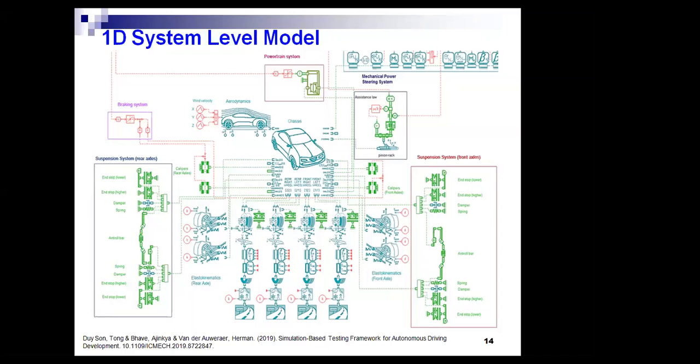Here it basically works based on an analytical approach. There is no finite element modeling or computational fluid dynamics involved in this one-dimensional approach. The one-dimensional approach is nothing but an analytical method, or is programmed as software that connects multiple subsystems.